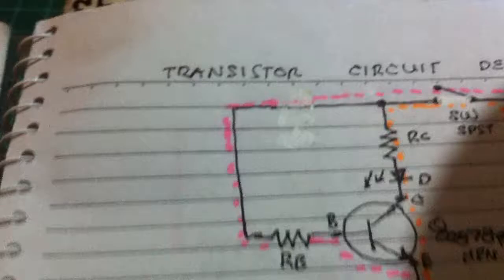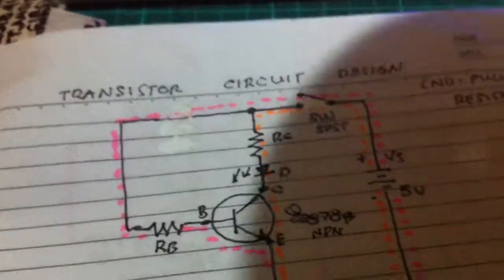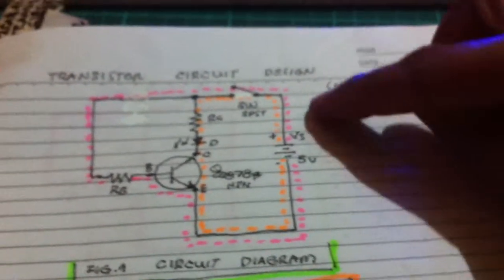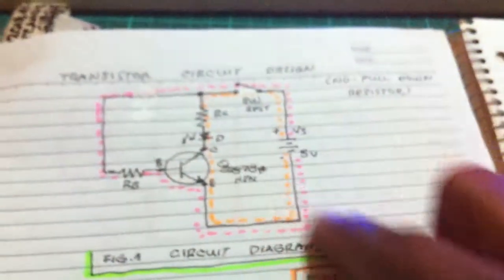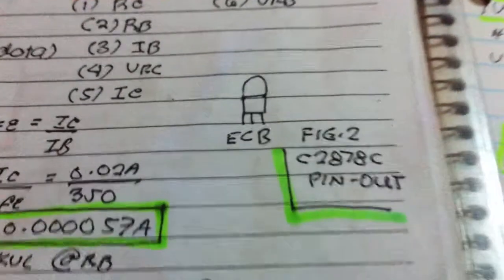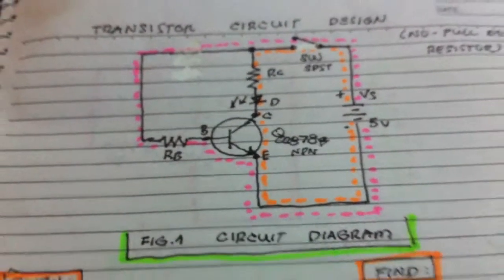And we have now this circuit, the red LED, and the circuit of that is transistor circuit design, and that is NPN. When you close the switch, current flows here and also to the base, conducting the transistor in saturation mode. And since this is also our previous circuit, we calculated all the values here, or some configuration, and that is our circuit design for that.